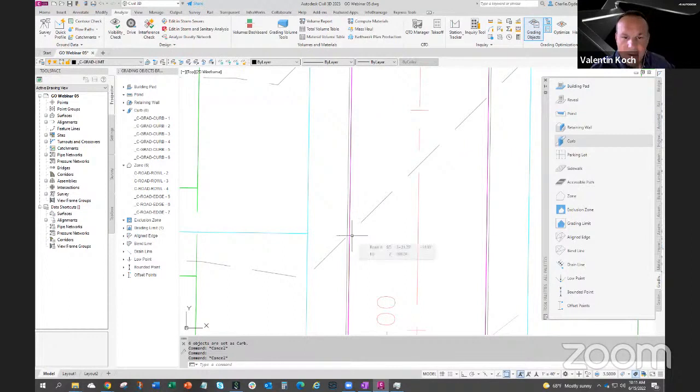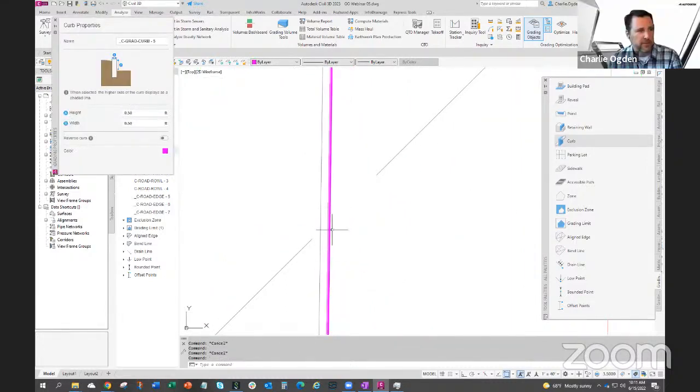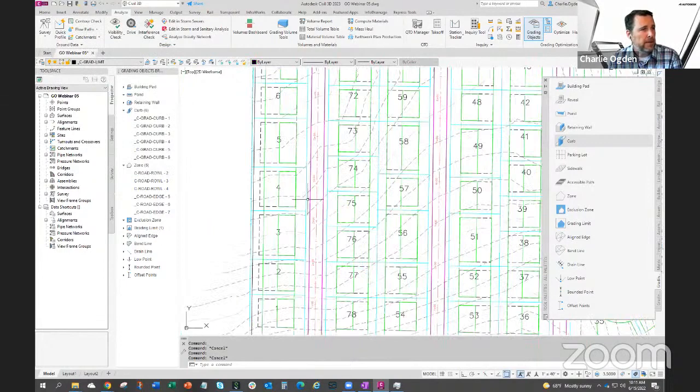You will see this will create a triangulation that is nice for crowning for our road. You will see that right away when you add the drain lines. Yeah, it's actually starting at the lower face of the curb, going to offset slightly to the top face of the curb, and then again the curb width to the back, right?